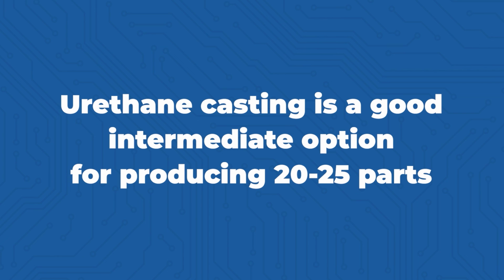Urethane casting is a good intermediate technology that allows you to produce 20 to 25 parts per mold. Obviously you can make multiple molds, but with urethane castings, they use a silicone mold, and it's a soft, rubbery like material. It just has a very limited lifespan. You can get about 20 to 25 parts out of it.